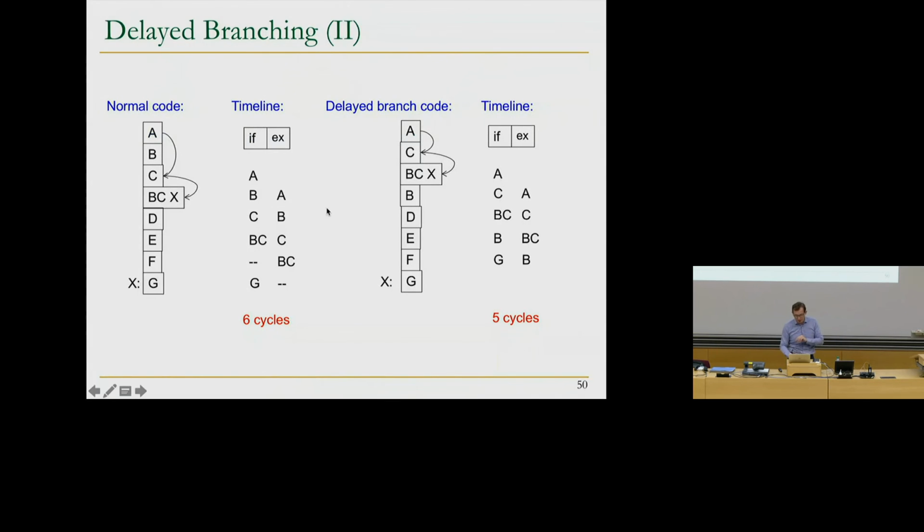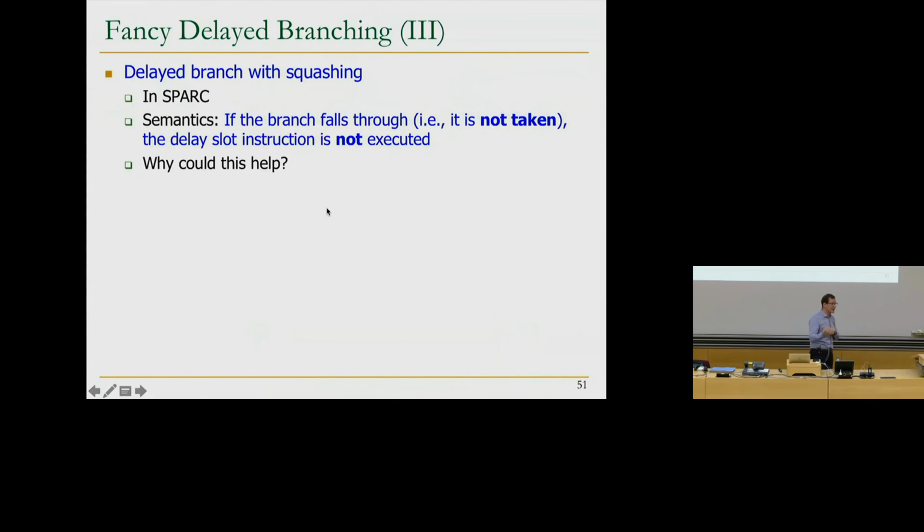So this is good, but people introduced, SPARC is another ISA that has delayed branching. MIPS is one of them. The early RISC ISAs, this is actually part of the RISC philosophy. The philosophy says, I want to minimize the hardware that I have in the machine, and I want to make everything the compiler's or the programmer's job, hopefully the compiler's job. You can think of this as part of that philosophy, right? The philosophy says, okay, why do I predict branches in hardware when the compiler can fill the pipeline slots with these independent instructions? Now let's take a look at another example.